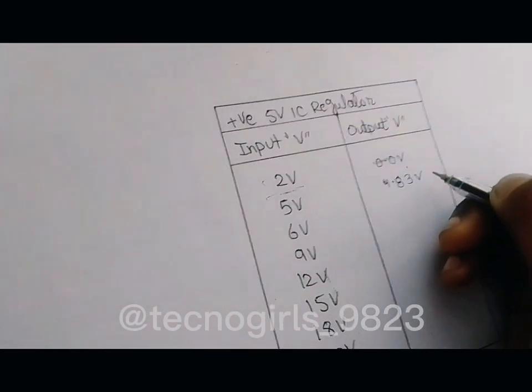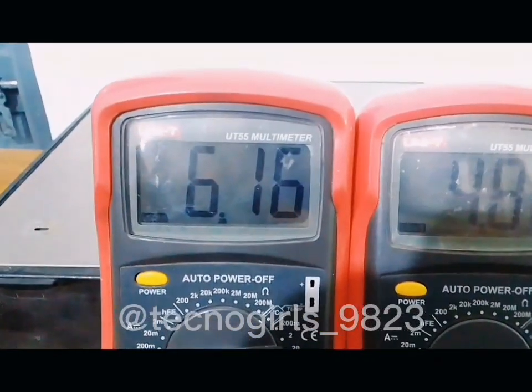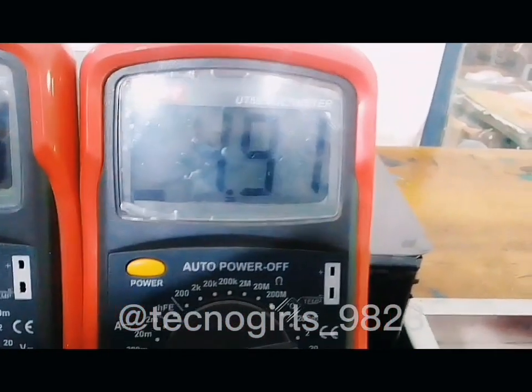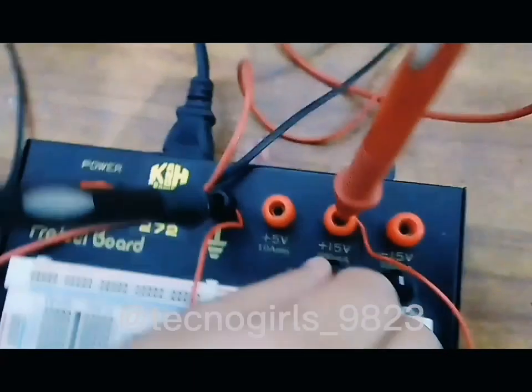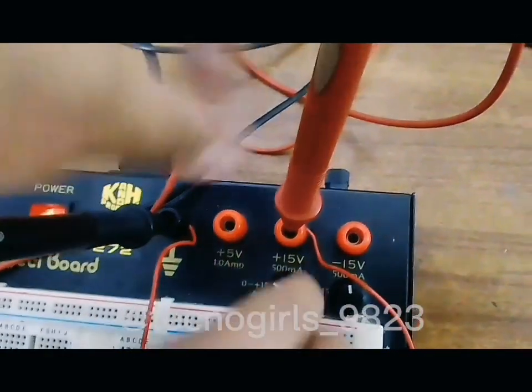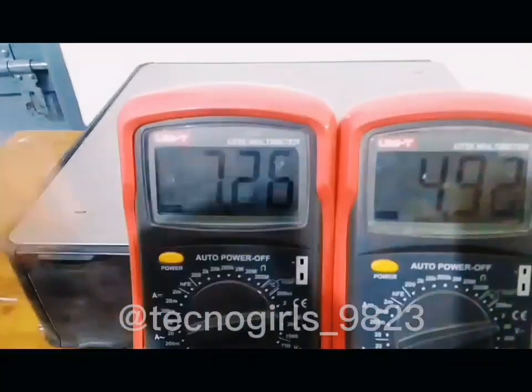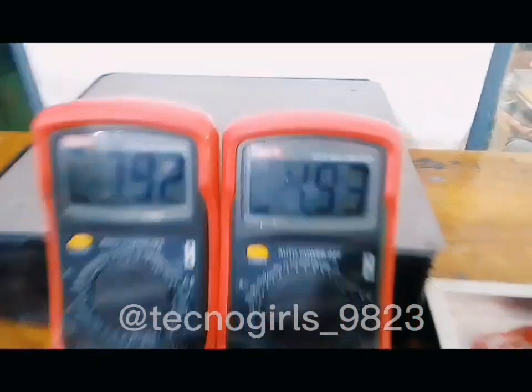It's roundabout 5 volts and let's apply 6 volts on this table. According to the table, we applied 6 volt and the output is 4.91 volt. Let me tell you, we just changed the input voltage from this knob. We just rotate this knob and the input becomes variable, and when the input varies, the output will also vary.